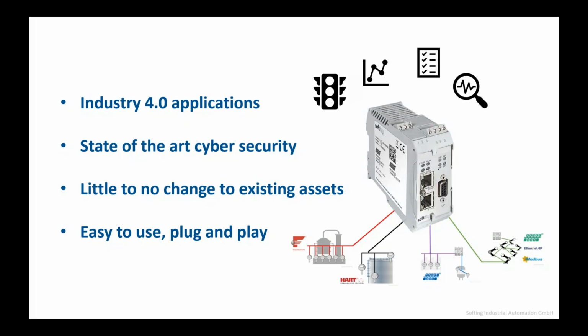There are certainly other possibilities to access the data right now in those types of systems. One would be installing some kind of an edge computer, like edge gateways, edge computers. This is mostly talking about edge computers. They definitely have advantages, as they are more open, and it's a computer after all, so it's not like a proprietary device. But this also bears a lot of disadvantages, because they are fairly more complex. They need more monitoring, people who really know what they're doing, people who host